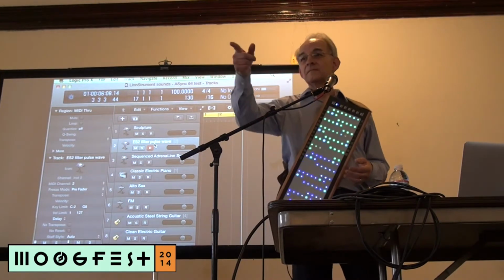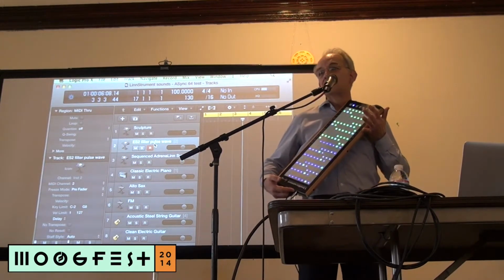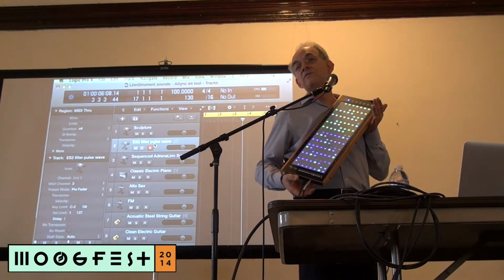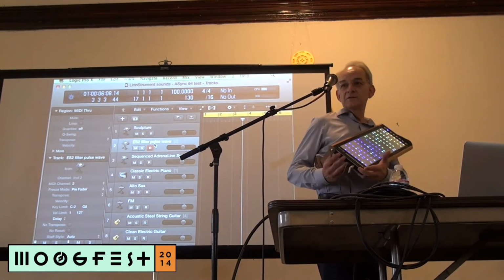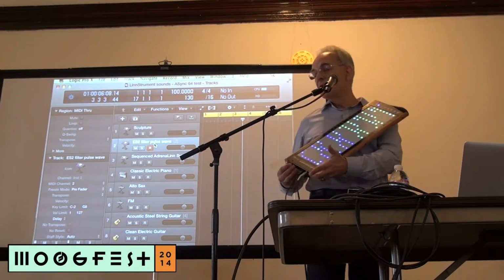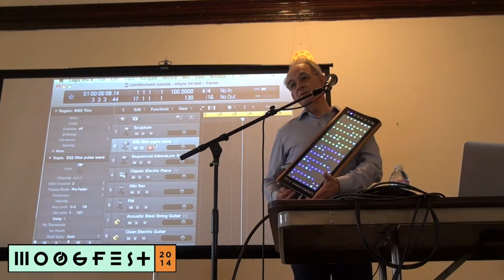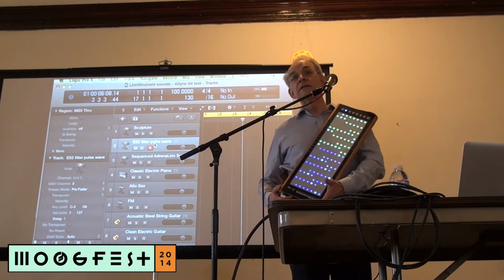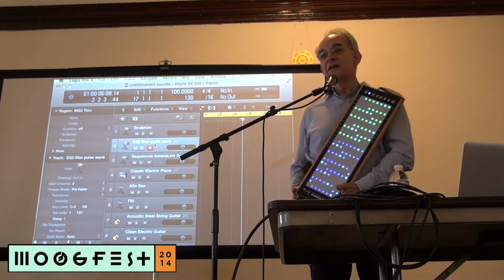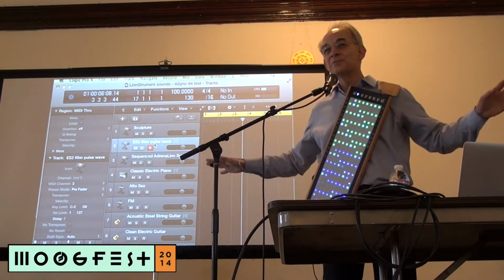How is it powered? Oh, this is entirely USB bus powered. So the only thing connected right now is a USB cable and the switch input. But there's also normal MIDI in and out if you want to be slower. Oh, and there's also a power jack. So if you're using MIDI in and out, which doesn't have power, of course, then you plug in a power connector, and it'll take AC or DC, center positive or center negative, anything from 7.5 to 12 volts. So you can no longer plug in the wrong supply.